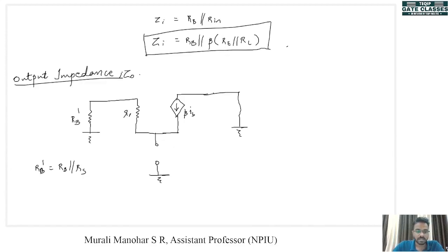So in circuits that contain control sources, we can find out the value of R Thevenin across this by applying a voltage source here, a voltage source of unit magnitude, and then we can find the current that is flowing here. If we divide the voltage by this current, we will get the value of R Thevenin. Right? You might be remembering this. So we need to find this current I. We can apply KVL in this loop.